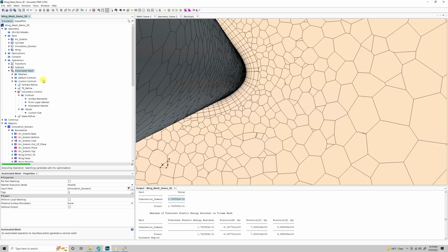For example, if none of the cells are making it to the maximum cell size, maybe doubling or halving the cell size actually doesn't hurt all that much. Because, yeah, sure, the cells really close to surfaces get smaller, but the cells further away are going to get a lot bigger. So it'll increase your cell count, don't get me wrong, but it might not do it by as much as you expect.